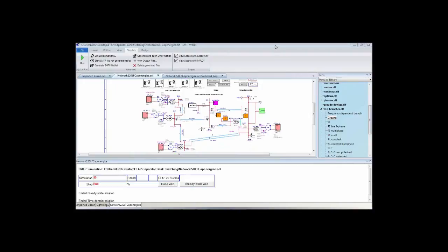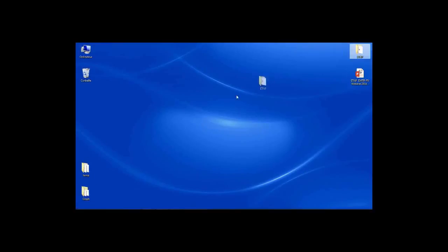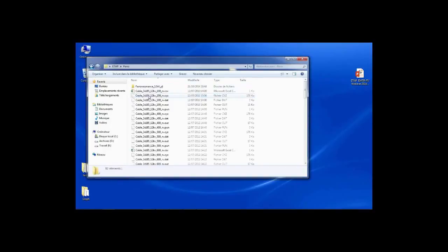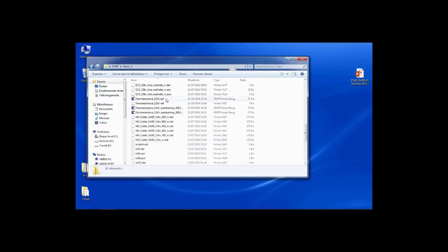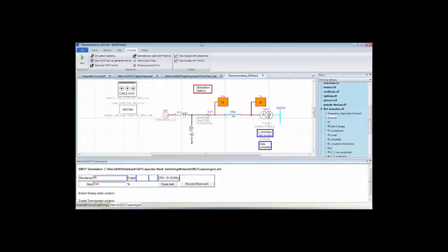Finally, the last thing that I would like to show to you is a ferroresonance case. Ferroresonance is a very dangerous phenomenon that can appear on power systems, and that basically occurs when a transformer is resonating with the cables, when the saturation of the transformer resonates with the capacitance, usually the cables.